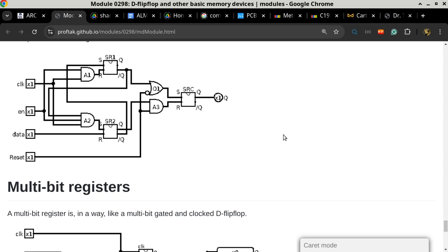All right. So does everybody understand how the reset pin is capable of resetting the final stage, the last stage SR latch, so that it starts with a known state of zero whenever the reset pin goes to zero, in this case? Yes. Yep. It bypasses everything.